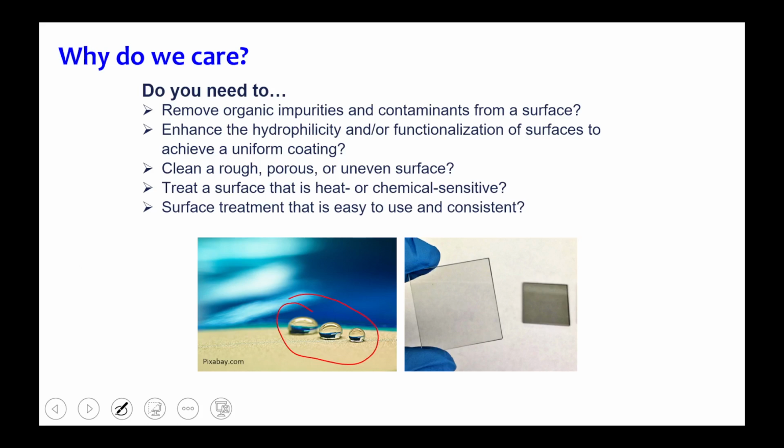Shamlal, you have to ask me a question about organic and inorganic. This is the glass substrate. It may be an oil droplet or any organic material droplet, or acetone, ethanol, methanol that we use in the cleaning process. Some contamination will remain after we rinse in DI water.